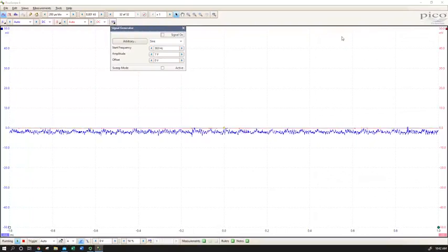So if I were designing a circuit where I needed a particular value of inductance, or I needed to know that my inductor had a particular value plus or minus whatever, plus or minus 5 or 10%, this wouldn't probably be the best way to go. There could be a huge, broad range of values that could vary with current, could vary with frequency. Nonetheless, if I needed something that was order of magnitude range, where I could maybe tolerate that broad range in actual inductor value, these might work just fine.